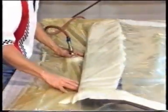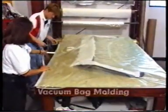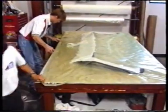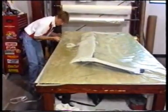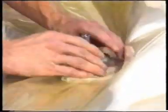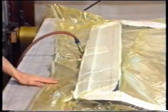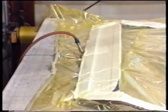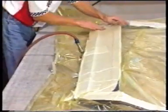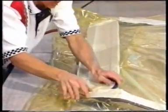Layups may also be consolidated and cured using vacuum bag molding. In vacuum bag molding, a non-adhering plastic film, typically polyester, is sealed around the mold plate and layup material. An air valve or valves is then added to the plastic film for vacuum connections. Once ready, a vacuum is slowly created under the bag formed by the film. This vacuum forces the bag against the layup, drawing out entrapped air and eliminating voids. Additionally, it also draws out excess resin.